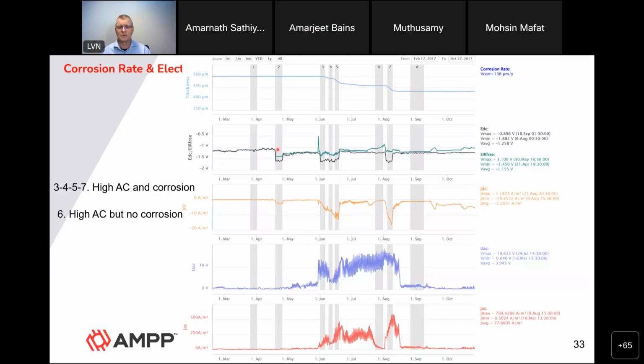First of all, we do a more increase of the CP, and we show that as long as you have no AC, you don't create any corrosion. So then we start disconnecting the groundings successively, and we can see that the AC voltage pipe to soil starts increasing, and there is a daily variation. Depending on the overhead power line load, we can see those fluctuations here.